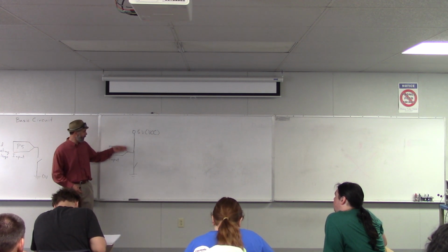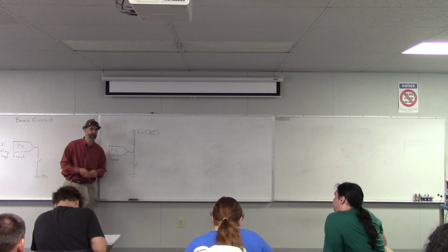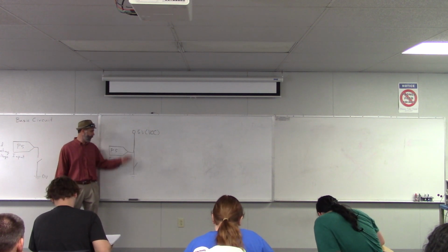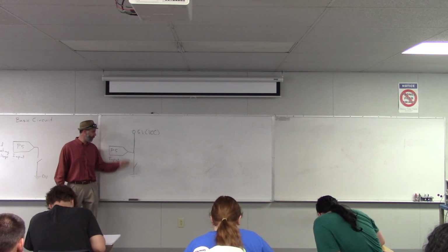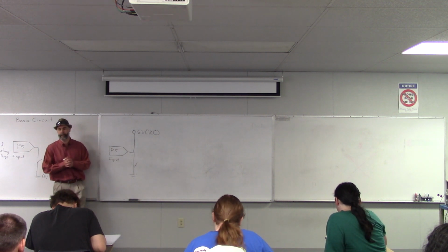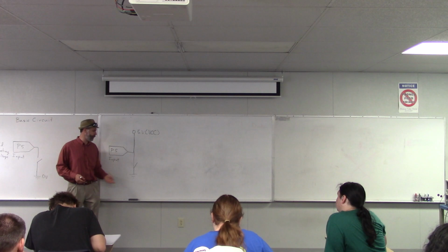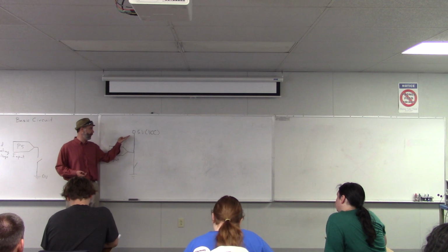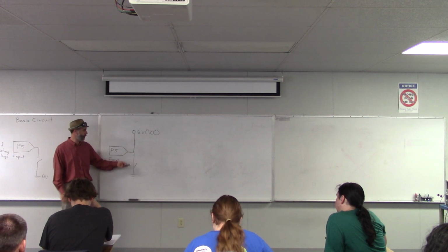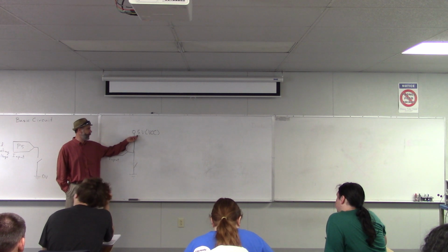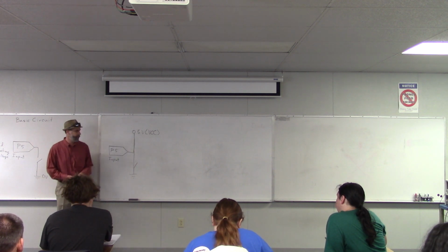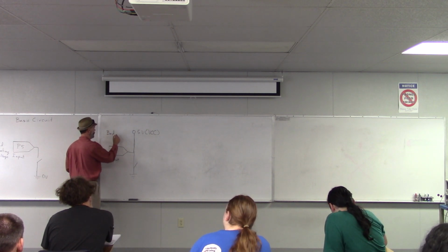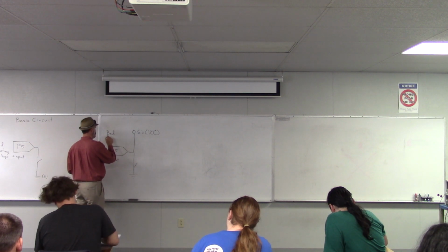So when you have a wire from power to ground, that's a short circuit. And what happens is that wire allows a ton of electricity to flow from 5 volts power to ground. There's essentially nothing slowing it down, so it just floods tons of electricity. And when a lot of electricity flows, things heat up, and that usually results in damage or destruction. So if you have a short circuit, that's going to probably destroy your power source. Okay? So this circuit is bad because it creates a short circuit.